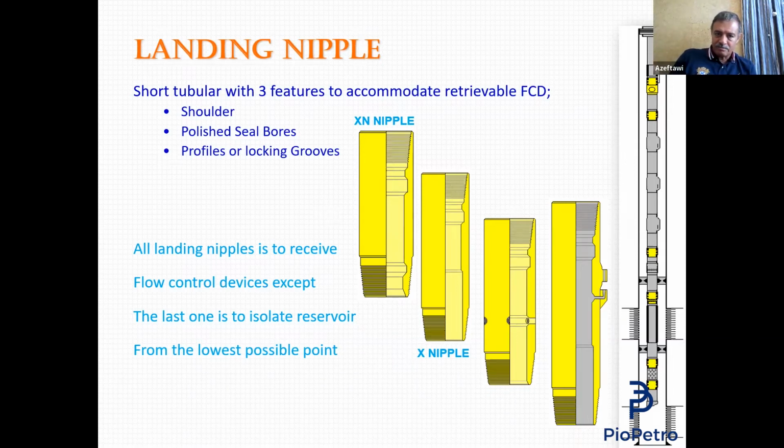Let's have a wireline plug, and we need to set it in the completion, in the last bottom completion here. So the wireline has the plug, and he starts running in the hole. While passing by all these devices, none of them will stop it because of size, till it reached the last one that would recognize this device. It says, "Stop, you are mine." What device will stop it? The shoulder. This is the reason why we have a shoulder.